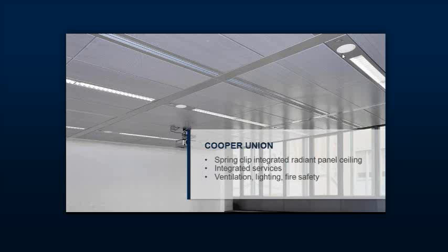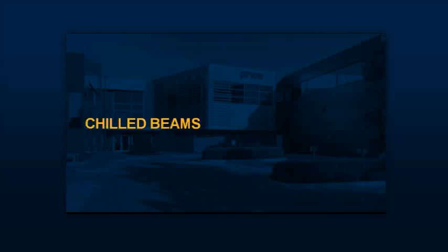And radiant is a very big part of our buildings, but it's not often considered as important as it's become in the last couple of years because of the amount of sunlight we're putting inside our buildings is taking some of the solar heat and moving it further in than we did 20 years ago. And the occupants' perspective is that they have all these different sources of heat, be it the window, be it the wall, the floor, other objects. They all interact. And as long as the occupant isn't aware of one being a strong source or sink, if you will, if it's cooling, then we can achieve thermal comfort.